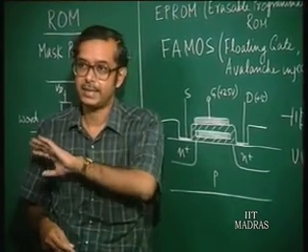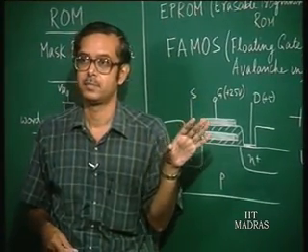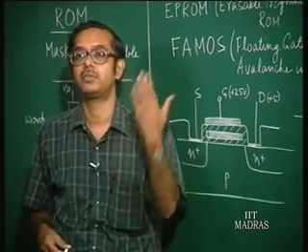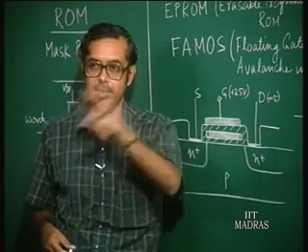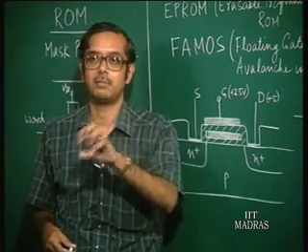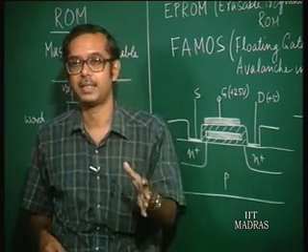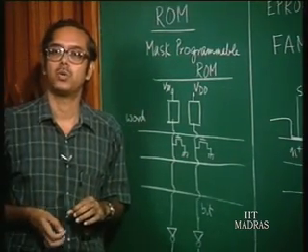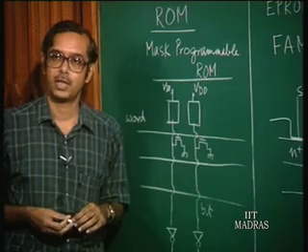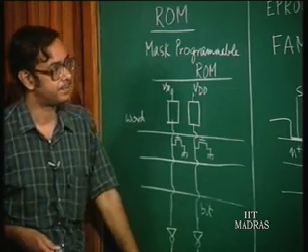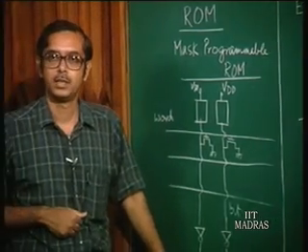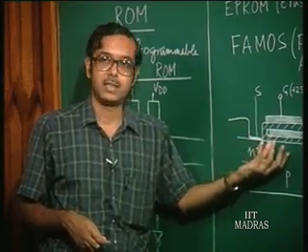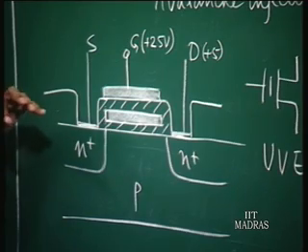When you erase, the entire memory has to be erased, and then again you have to reprogram the entire memory. It is not that if you have a part of the memory you can erase it. Whatever you had in the chip is removed, and then you have to reprogram the whole memory. So, that is the problem.